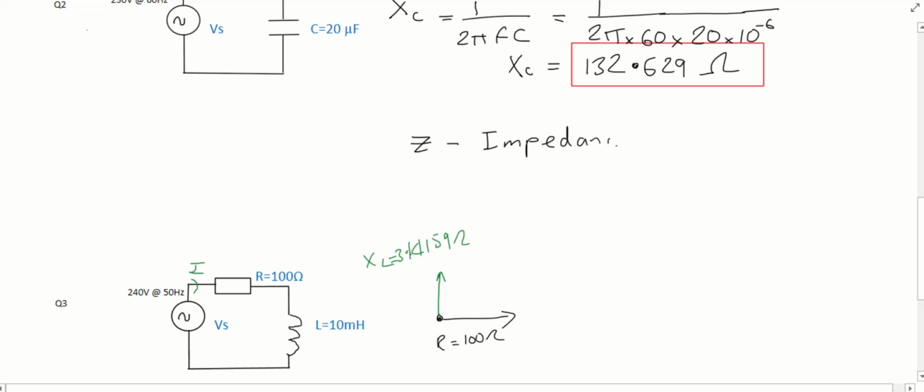So that is the total AC resistance in the circuit. So now if you wanted to work out what Z was, we would use the same method by doing a resultant vector here from the phasor diagram, and this angle here would be equal to the phase angle.